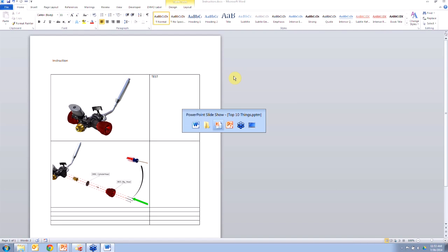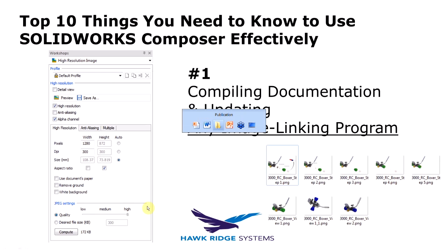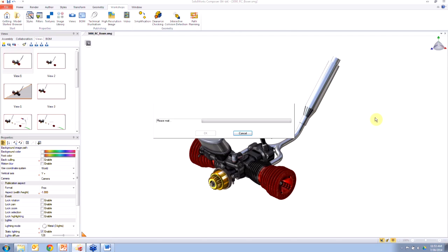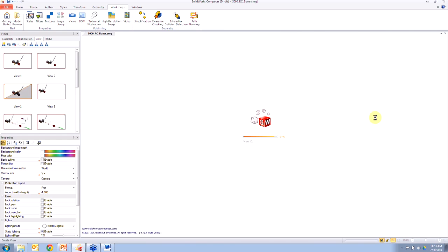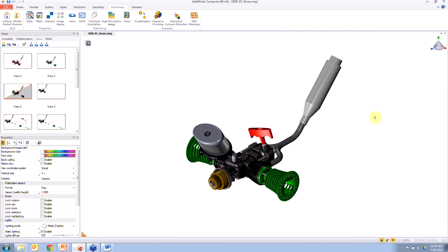One piece of key advice, I guess, is the update and import options. That's the merged file, the one actor per part, the merges or import as bodies. You want that to stay consistent from import and update. If you change the options between the two, it can cause kind of goofy results. So just make sure that if you're seeing update issues, that's probably what's going on if those options have changed.